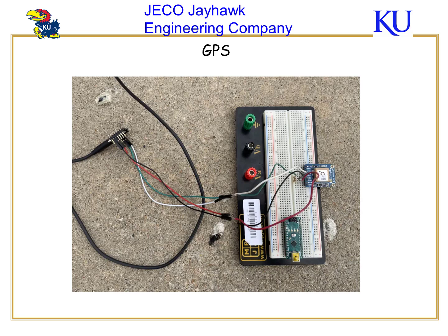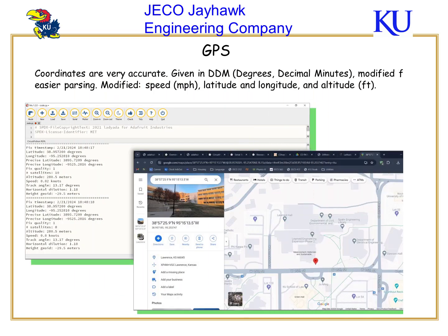And that basically powered the GPS, and we're able to also provide information from the GPS to the MCU via those pins there. So using CircuitPython, we're able to program our MCU and retrieve this data from our GPS. At first, we had an output signal that was just in our terminal, but later on, we were able to parse it slightly to get more accurate data, as you can see here in the picture on the left. And it's a lot easier to read, but it spit out all sorts of information, including the number of satellites, how well it fixed, longitude, latitude, and things of that nature.